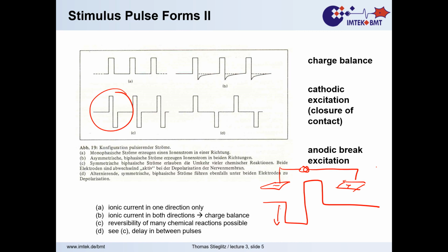There are some people who would sell their mother saying there's only one electrode. And then if you look it up, you find the ground connection between that electrode, the charge generator, and, for example, the ground of the operation theater table, which is made out of metal. That means the circuit is closed by that. So we have to take care from the engineering side to find that second contact and to understand where it's closed.